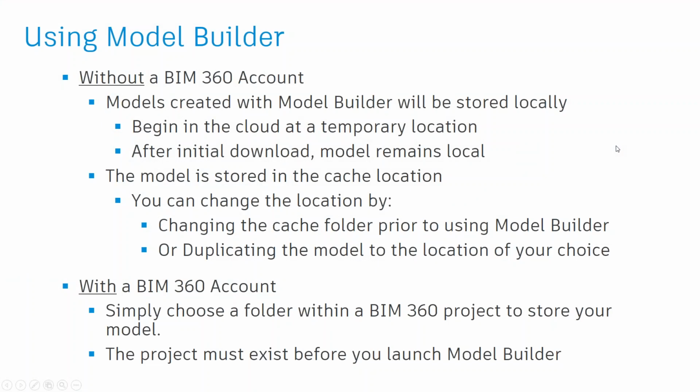Well, the really good news is if you're not set up with BIM 360, either you don't have an account or you just haven't worked with your contract admin to get added yet, no problem. You can still use Model Builder without a BIM 360 account. What'll happen is it'll go through the process just like it always does. The model will start initially in the cloud in kind of a special account that we've created for this purpose. And then after you've opened it the first time, it'll just become a local model. No problem.